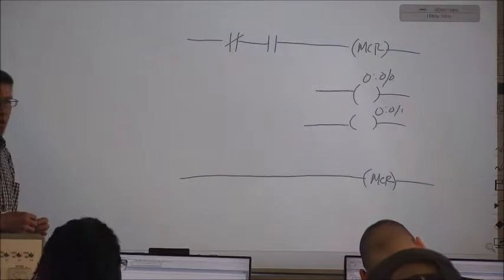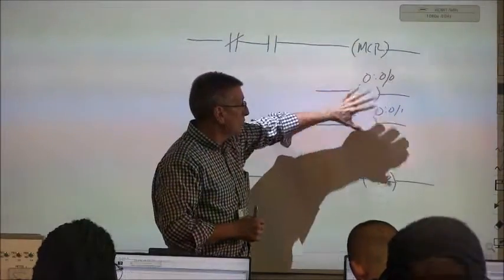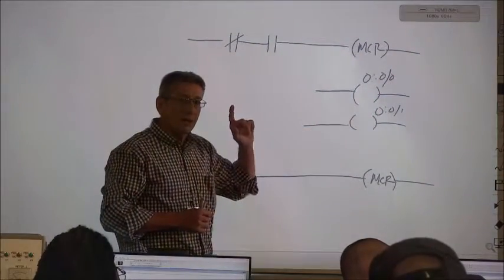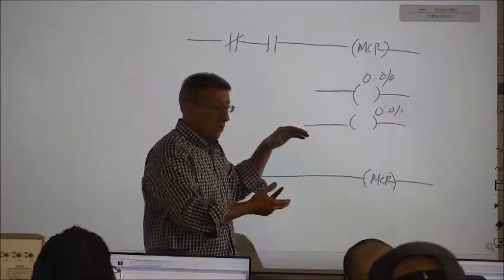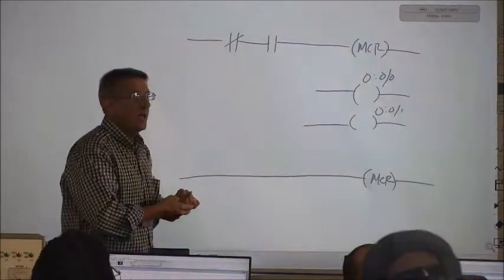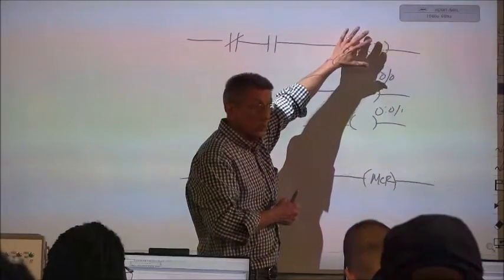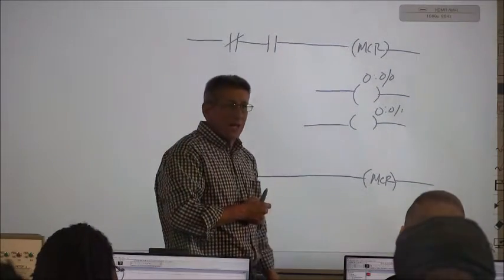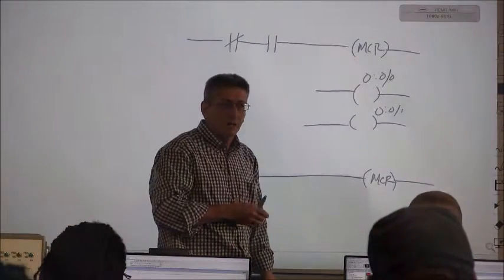Yeah, so here's what happens. This first rung has to stay true for these outputs to even be scanned and energized, right? Here's the key: if any of the outputs inside this zone are energized, and then this first MCR instruction goes false, it's going to de-energize those outputs. Good? It's just like an MCR on a machine, right? The relay logic. Did we talk about that a little bit?